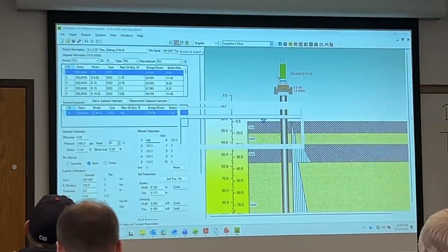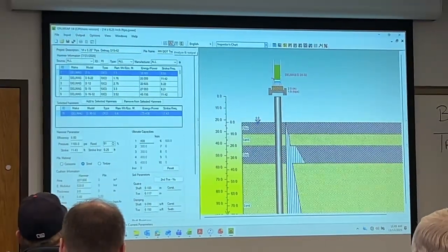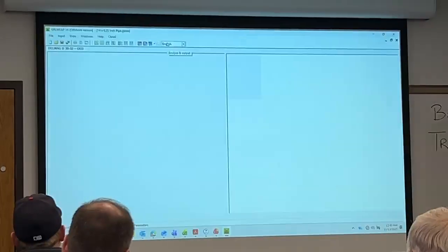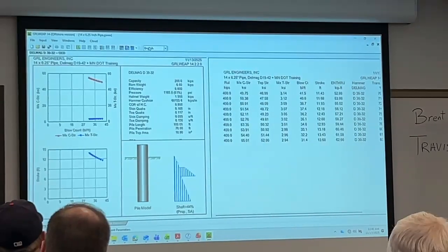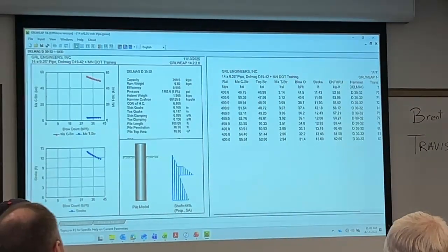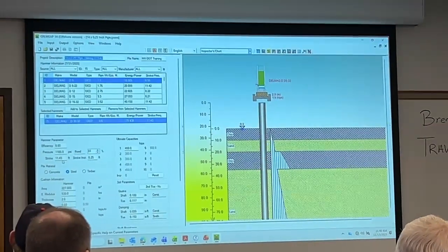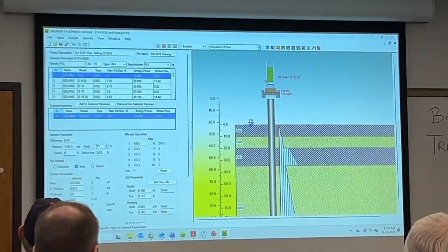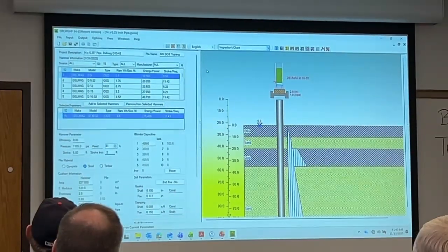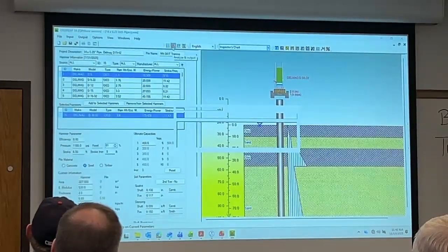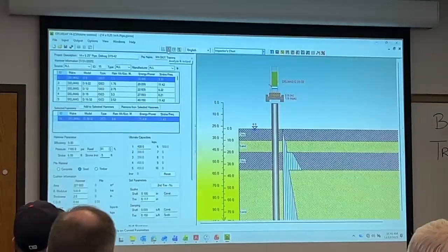So a diesel hammer is not going to transfer more than 80% of the rated efficiency, right? Because a diesel hammer transfers 50%, when 55% is a really good hammer. So go back one more time, Travis. Okay. And under your hammer parameters for strokes, let's make it fixed. Start it at 6. Instead of letting it run a bunch of goofy things, you can do 6, 6.5. I should have done that. Thank you. So now we're looking at all the combinations that will achieve 400 kips.